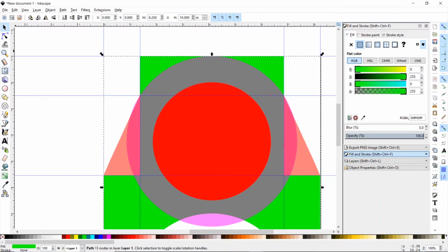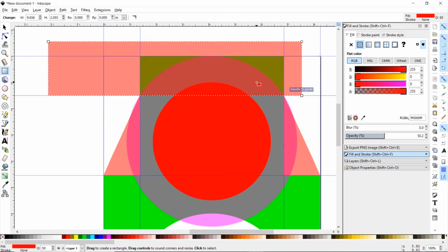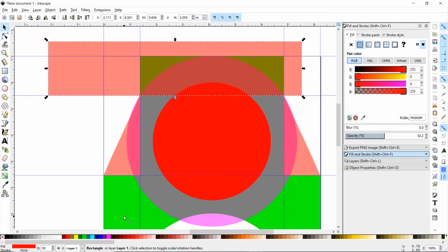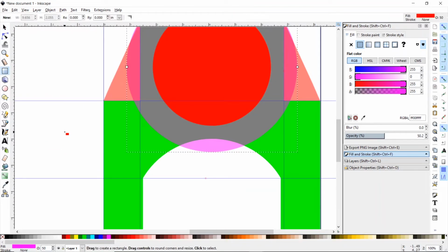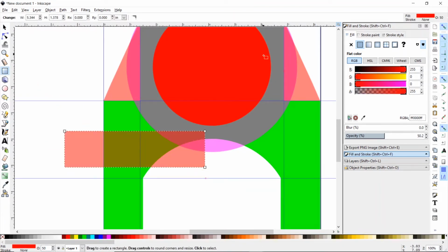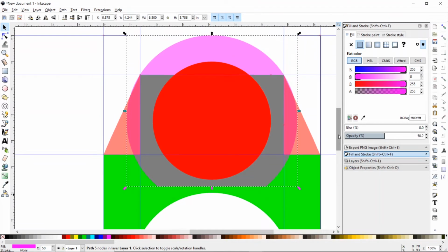And now I'm gonna take off that top section too, so let's create this. Snap to there. I'm gonna say select that and select this, path difference. Remove that chunk real quick. I'm just going to make a piece and delete it. And I'm going to turn off my snaps because I don't want it to move around on me. Alright, so I'm going to select it, select this, path, difference. Alright, now it's no longer showing up down there.